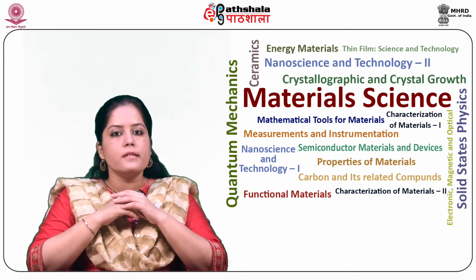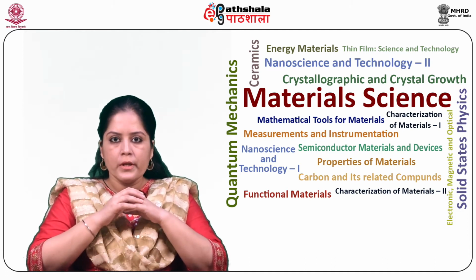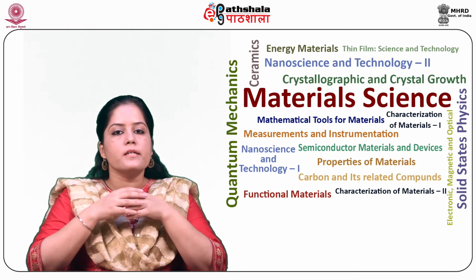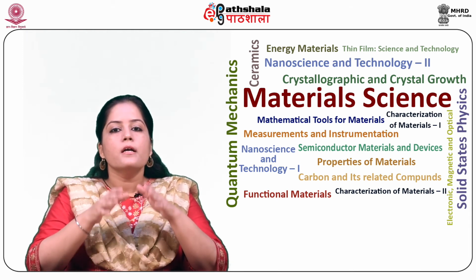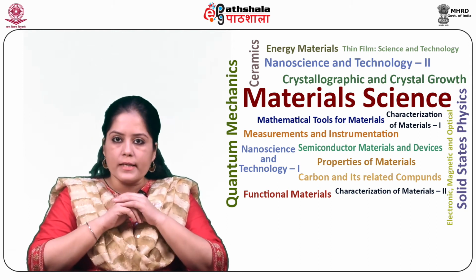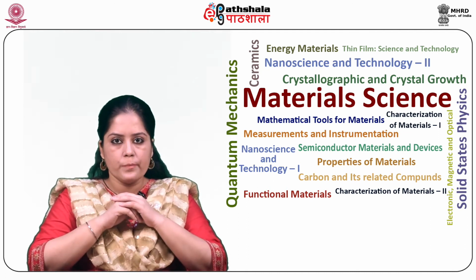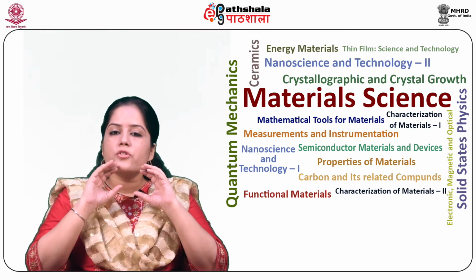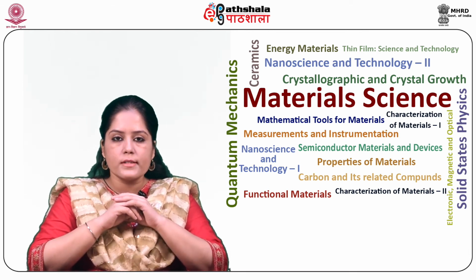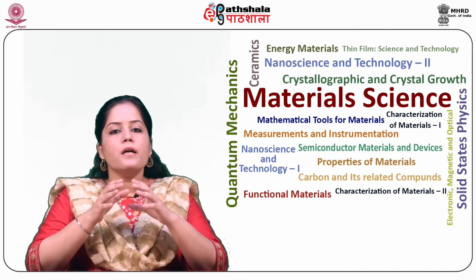X-rays produced in the synchrotrons are ideally suited for proximity lithography because they are naturally collimated. So rays produced in synchrotrons do not cause penumbra, and they produce deep resist profiles with vertical sidewalls and astonishing aspect ratios. In addition, because of the extremely short wavelength of X-rays, diffraction effects caused by the mask substrate gap in proximity printing are minimized.